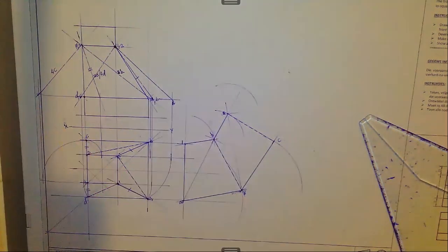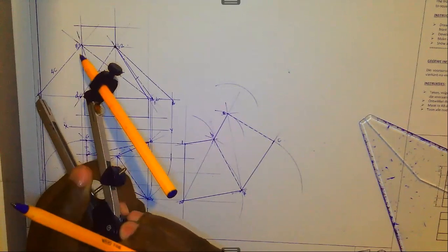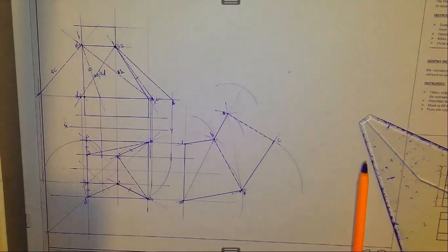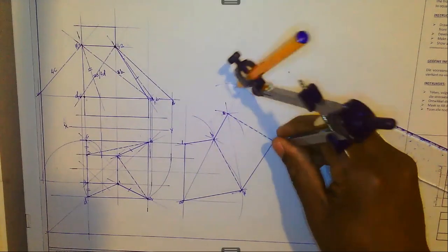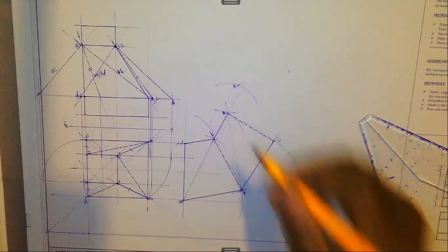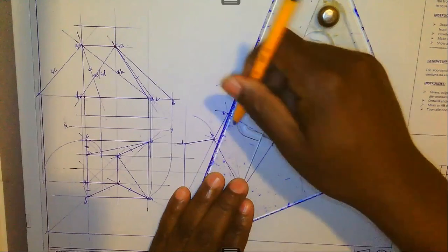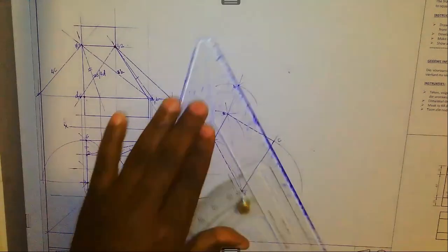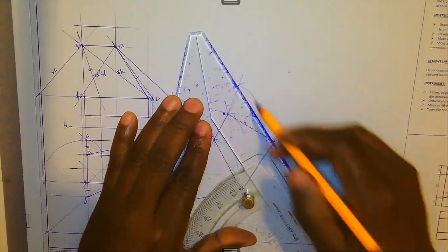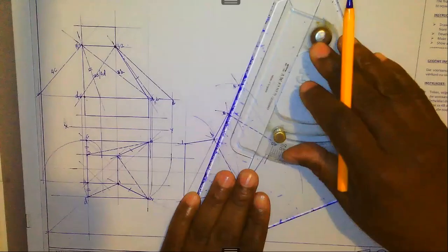So I'm going to take this true length like this. You stand at point C and you describe an arc like that. There you go, you get a point. That point is point number 4. You connect this point to number 3, like this, okay? And this would also be connected to C, like that. Now, this can be outlined. It's a cut line. So I'm going to outline this.